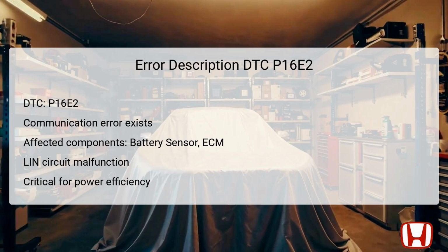If the LIN communication is disrupted, it can lead to inefficient power management, which might affect engine performance and overall vehicle stability. Detecting this error requires the use of the Honda Diagnostic System, HDS, for accurate diagnosis and troubleshooting.